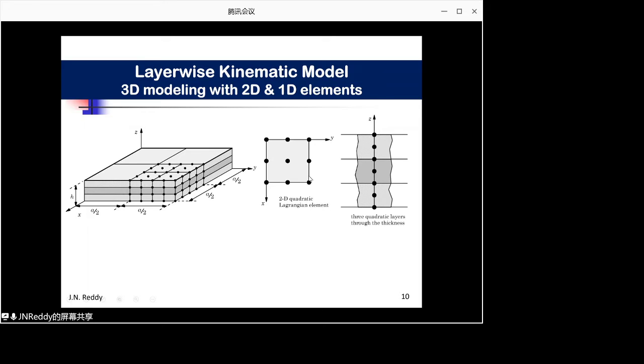And the middle layer takes no stress at all because they are not in the direction of the stress. So 90 degree means the fiber is into the screen, whereas 0 degree means they are along the in-plane direction of the stress, sigma XX direction. So if the structure is very thin, all 3 layers will have one continuous straight line going from bottom to top here.